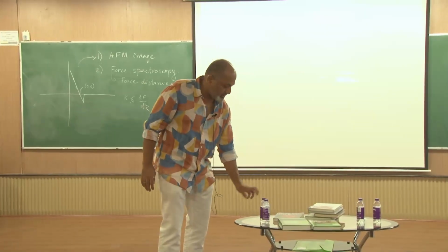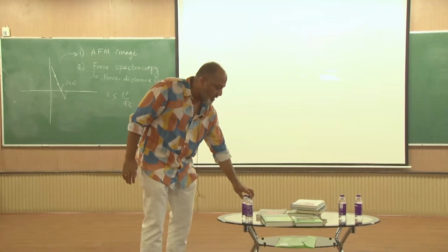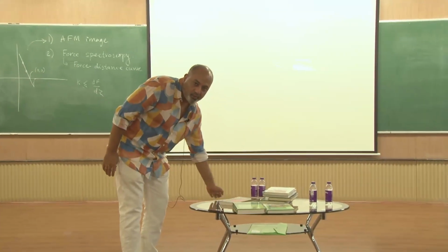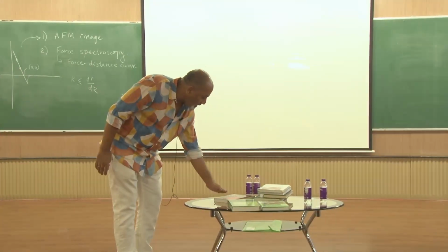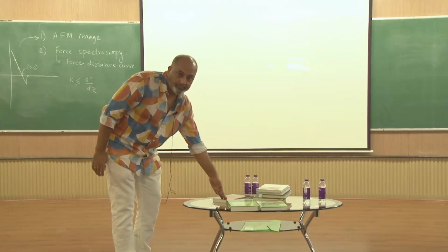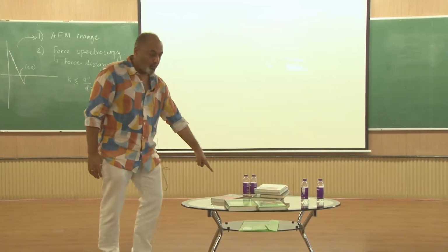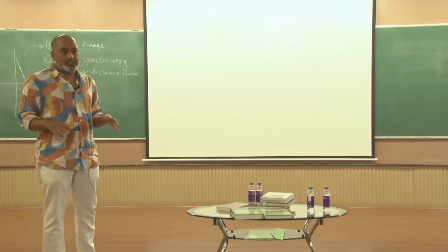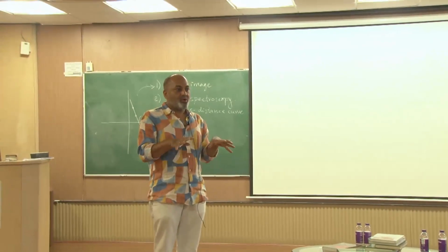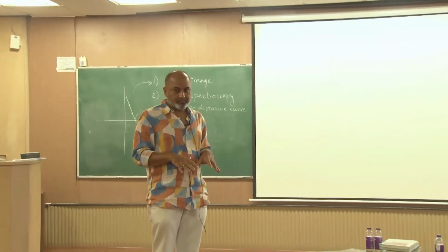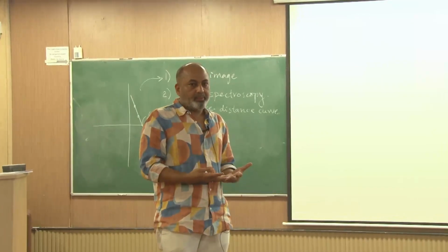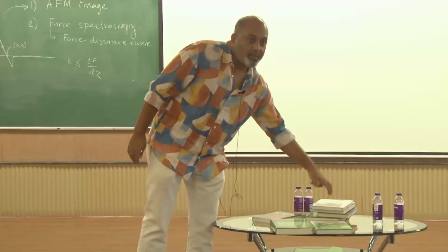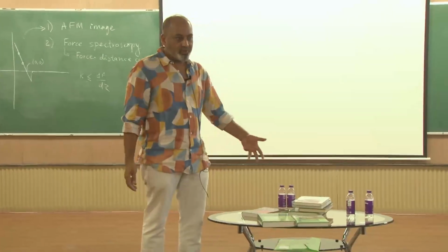You either topple it, depending on how strong it is, or suppose this is like a book that is too tall, but suppose this book is not getting toppled over. So you have to come to this and come up again. So the load becomes suddenly high. So low load, high load, again low load, and then again high load, and so the whole image is not taken at a constant force or constant loading. This creates a problem, particularly for specimens which are, like this book, softer compared to the glass, and the load is then difficult to work out.